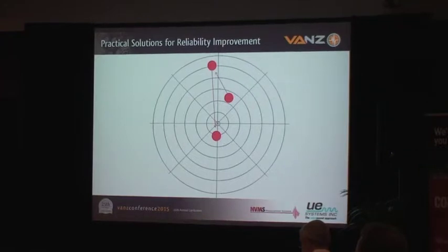These things don't fix themselves. In reality, the first step change was a single blade loss on the fourth wheel. The blade that broke was actually about the size of this clicker. The next day, the event that happened was two blades on the opposite side of the wheel. So it's like it kind of tried to balance itself back. I could just see the turbine rotor as it's going around going, oh no, that wasn't good. I better shed a couple more over here to bring it back down.